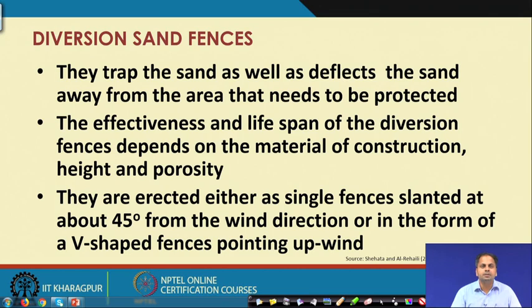Sometimes they are erected either as a single fence at 45 degrees from the wind direction, or in the form of V shaped fences pointing in the upwind direction, so that we can deflect the quantity of sand away from the region which needs protection.